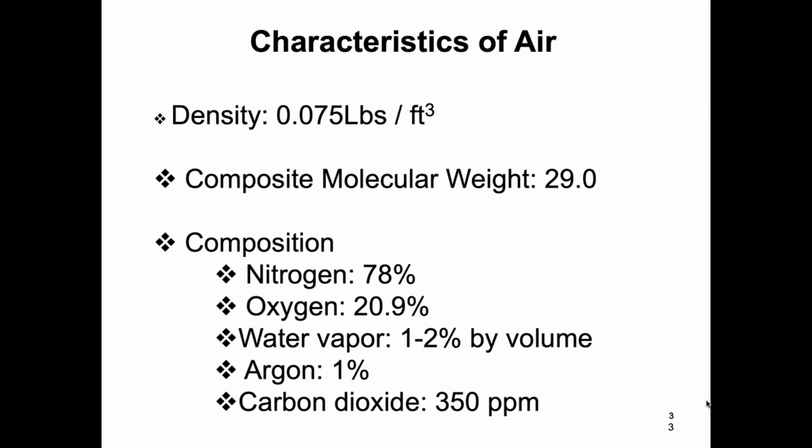When you get into industrial ventilation, you're not going to use that particular formula, because almost all the measurements you're going to work with in the United States are going to be in US units. So you're going to learn pound moles, how much space a pound mole of air takes up. In other words, 29 pounds of air takes up so much space. I don't remember it off the top of my head because I usually work in the metric system, but if you're a person who works with industrial ventilation systems or HVAC systems, if you're an engineer that designs air conditioning systems, you're working in cubic feet per minute.